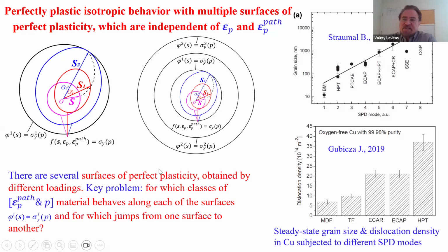But you know what you said, these metastable non-equilibrium phases which don't correspond to minimum energy, we produce them under shear. So we produce silicon, for example, silicon 2 at 0.3 GPa, while the phase equilibrium pressure is around 10, 12 GPa. I am not talking about the phase transformation pressure under hydrostatic loading, which is 16. And we produce it at 0.3. Of course, we produce strongly metastable phases.